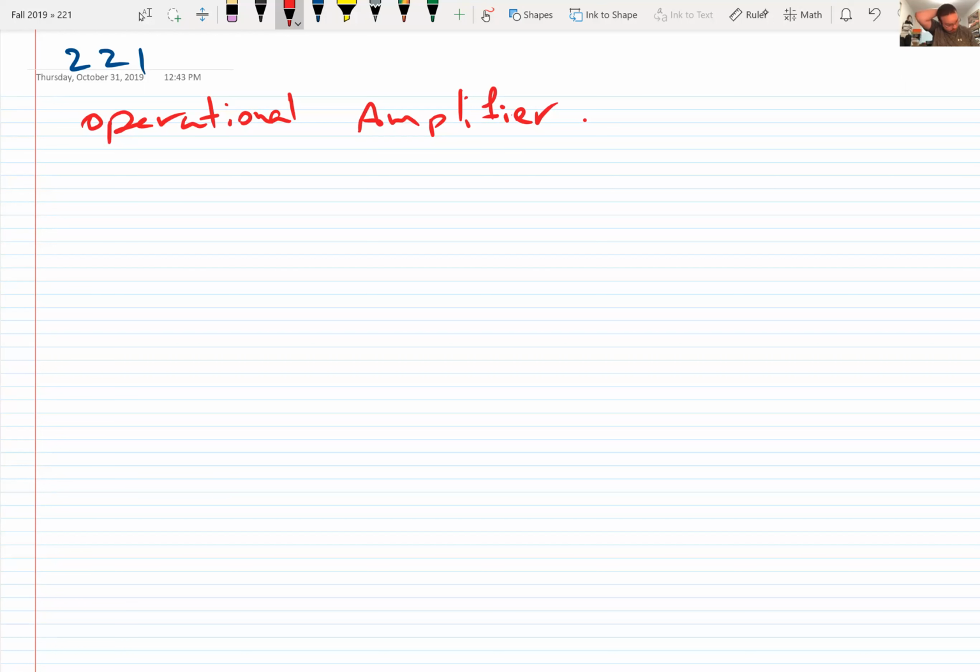And if you remember when we discussed the voltage gain KV, I said that KV is the output voltage over input voltage, and the same thing for KI, which is for current sources: output current over input current. We know that these voltage and current gains are definitely less than 1 for circuits with independent sources. But if we have dependent sources, this gain can be more than 1, okay?